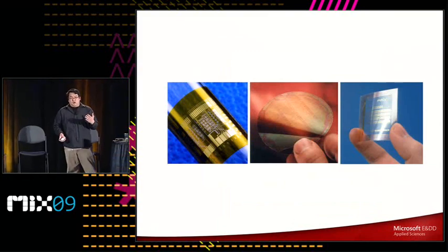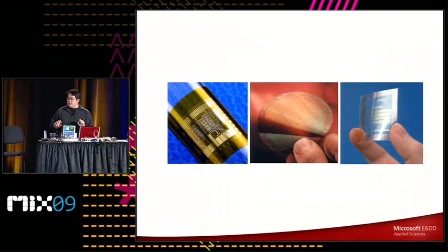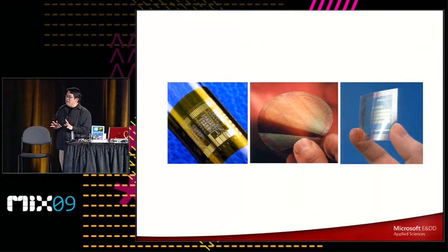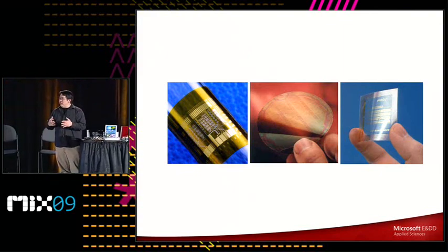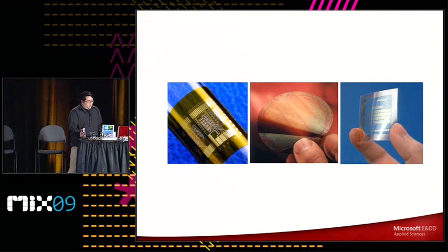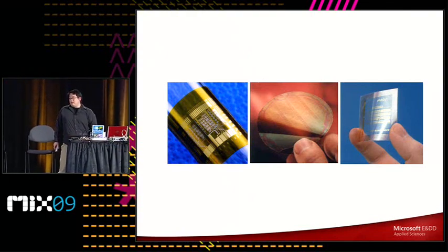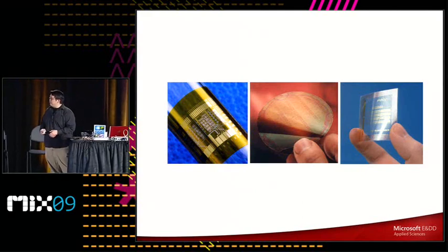And the limitation is largely what's called the backplane technology. It's not the light emitting part or the part that generates the display. It's the part that actually actuates those pixels. So it's all the transistor arrays and all the plastic logic that has to go behind it. And this is the part that's fragile, and this is the part that doesn't quite have the performance yet. But it could with some material science. But it's unlikely to ever become truly foldable as paper is without breaking.